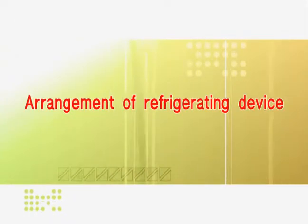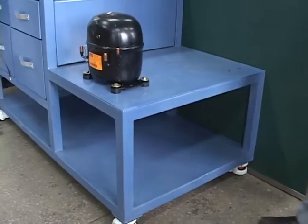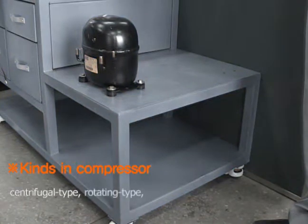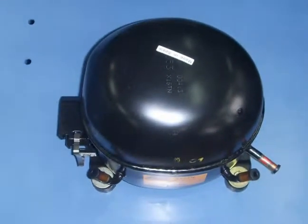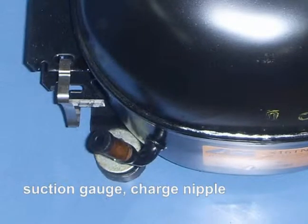Now I will explain the arrangement of the refrigerating device. First, we will fix the compressor on the table. There are various kinds of compressor, such as the centrifugal type, rotating type, vane type, scroll type, screw type, and reciprocating type. We use a piston reciprocating type compressor in this test. This compressor has 3 protruding holes, 1 big and 2 small. The big hole is the compressor suction hole. The upper small hole is discharge, and the lower small hole is for the suction gauge or charge nipple.